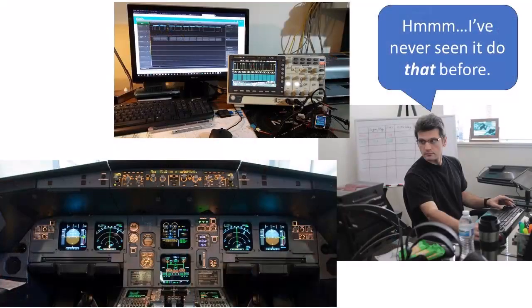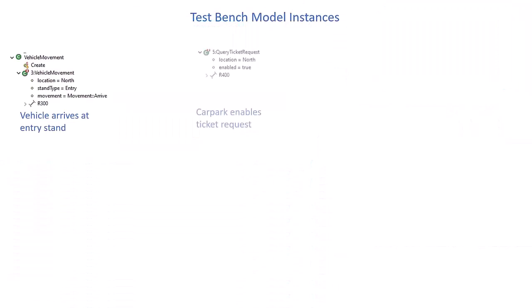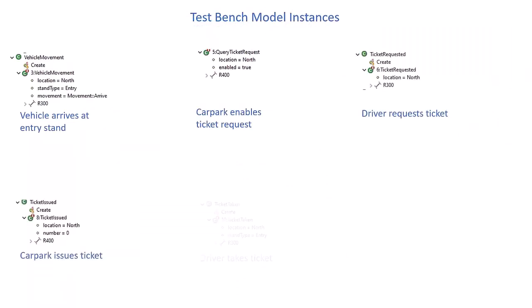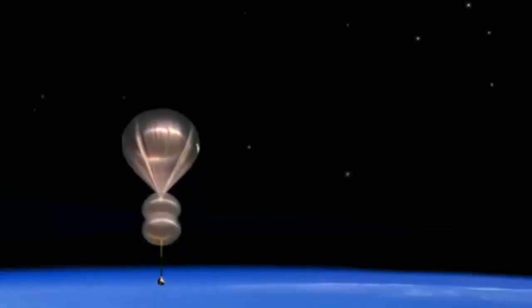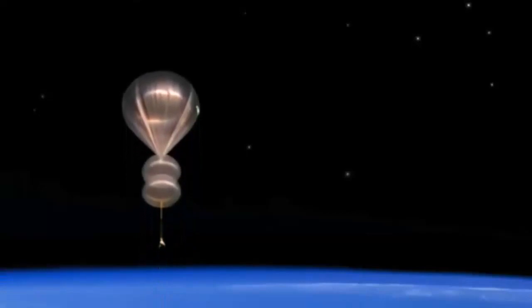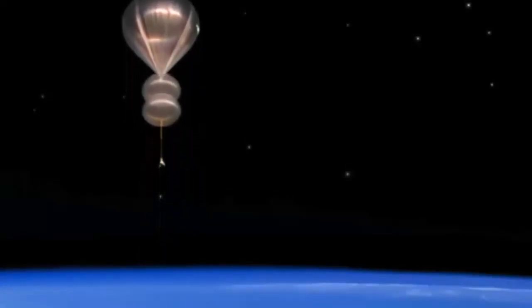Visibility and control of system components are a factor in deciding what to model in a test bench. Even when the deployment target is readily available, it may not be easy to understand exactly how your models interact with it. Test bench models give you excellent visibility into just how your modeled components interact with other components in the system. And some components of a system may be delicate and easily damaged when confronted by erratic control from an application that is yet to be debugged and verified to be operating correctly.